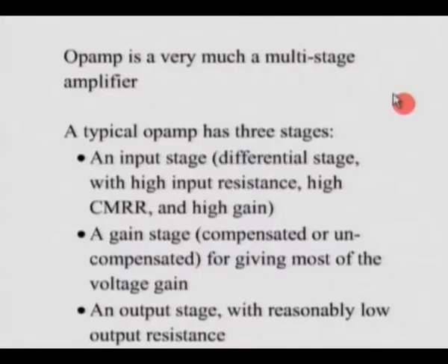Now once again, all op amps would have a third stage, sometimes the final stage, which is called the output stage. This particular stage is meant to drive an output load. Now 741 can drive a maximum current of about 20 milliamps. If you have to drive more current you need to add some extra discrete components, transistors, at the end.